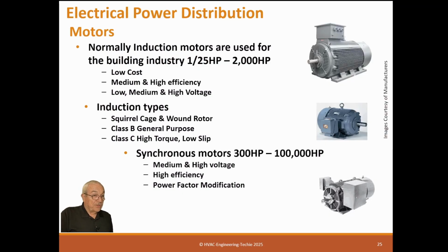That's why the motor turns, right? So in a synchronous motor, the rotor is trying to catch the stator, and it can't do that. It'll come within just a few degrees of that. And when it does that, it doesn't have any induction, so the power factor is 1. And on the controls on these motors, you can actually adjust the power factor on some of them. So that is interesting. You can actually modify the power factor.